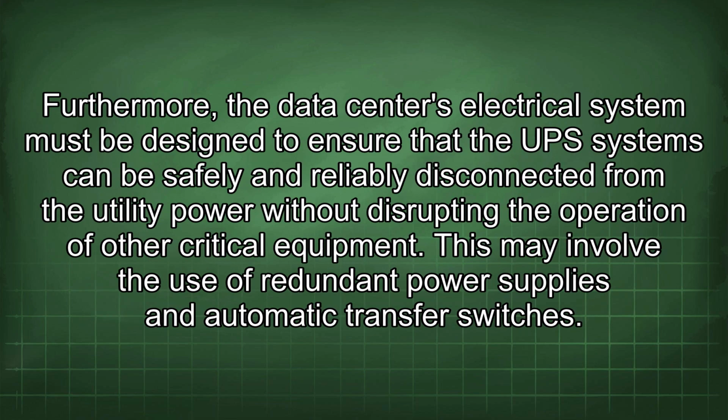Furthermore, the data center's electrical system must be designed to ensure that the UPS systems can be safely and reliably disconnected from the utility power without disrupting the operation of other critical equipment. This may involve the use of redundant power supplies and automatic transfer switches.